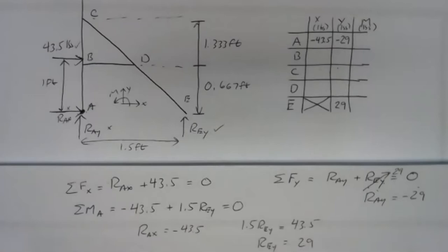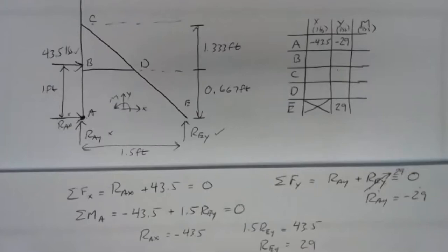But at least with this external problem, we were able to get 3 unknowns. So 3 of our unknowns are down. We only have 6 left, B, C, and D. Well, we can't see what's going on with B, C, and D in the external problem because those are internal forces. They're inside the bubble that determines where our system is. To expose the unknowns, we have to expand the frame. I like to think about it as blowing the frame up and looking at the individual pieces.